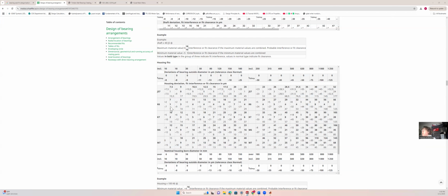So to figure that out, we're actually going to back this up with an equation here. We're going to consider for this equation that the diameter of the bearing is in fact its nominal diameter. We need to be somewhere in between the 2 and 10 thou, and it's unclear as to exactly how big to make your housing. So to find that exact answer, I've made a MATLAB code for the equation that you find in your lab manual that tells you the del. So del equals 2.5 times square root of FR times lowercase d over uppercase B.